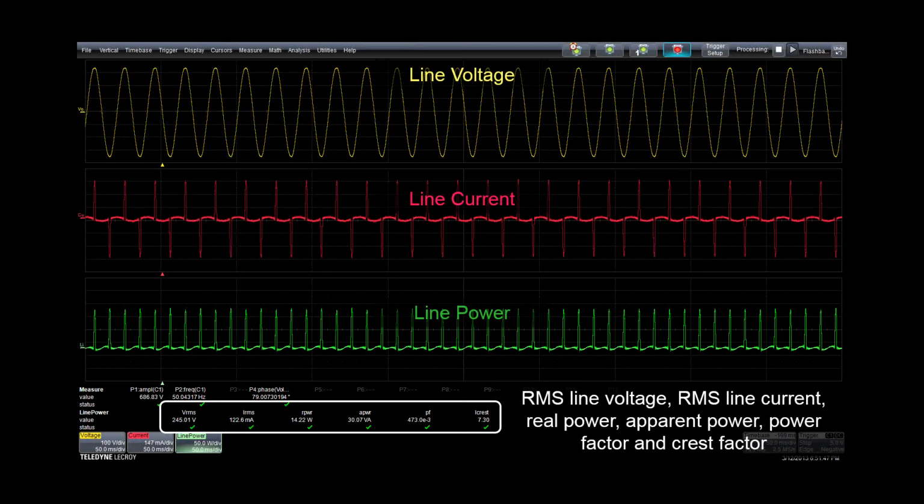And actually, it's also going to contribute to heating of the wire in the building that you're connected to, and increase the stress and the heating on the utility transformers, and everything going all the way back to the utility electric supply. So this causes not just problems for your particular device, but everything upstream.